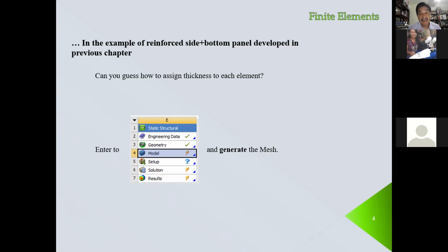If you select a very small size of the mesh, the number of joints is going to be extremely high, and it will take forever until you get results. So you have to be practical. At the beginning, you can accept a large element size. And then when you are close to convergence, you should go to smaller elements, okay?